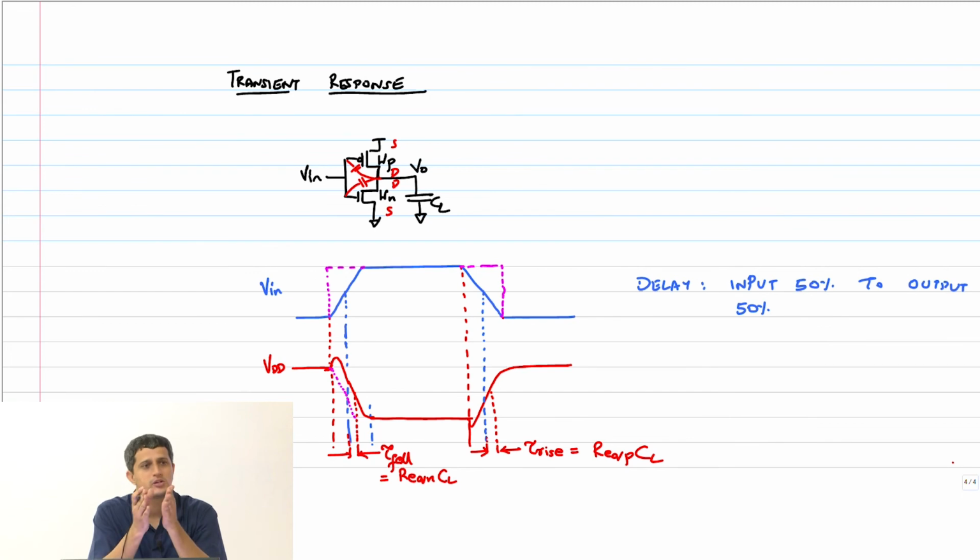No. See, the voltage cannot change instantaneously across the capacitor, right? So the C dV by dt, you cannot have an instantaneous change, which means that there is an infinite current otherwise. So to maintain that, the other end will also follow the input for a short while. This is a very high frequency switch that's happening when the input changes instantaneously. Therefore, the other plate of the capacitor will follow this node a little bit, and that's why that initial bump is happening there.